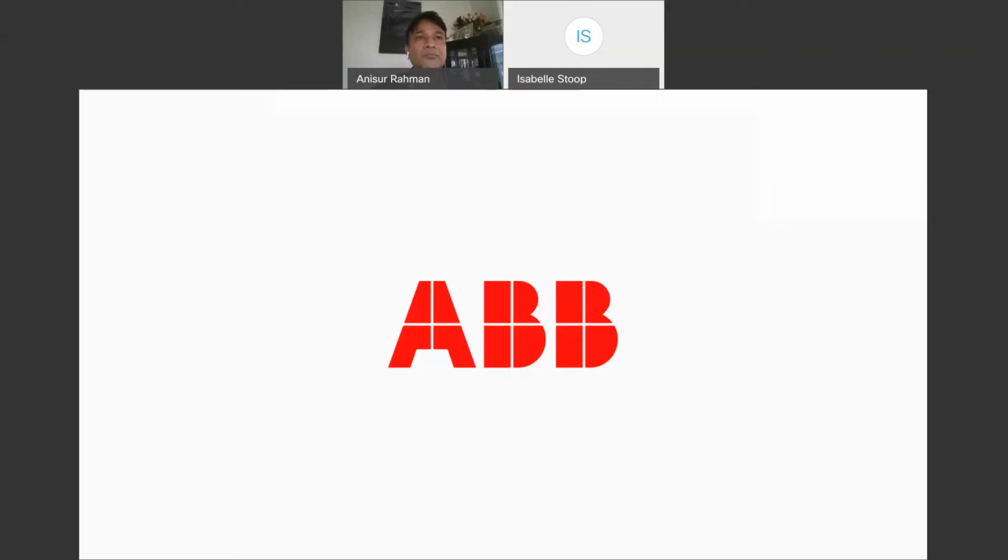Can we see the HMI from the central control room? Yes, it is just an Ethernet network. So you can use Internet Explorer or Chrome on any computer in the same network, type the IP address of the SSC 600, and you will be able to access that web HMI.